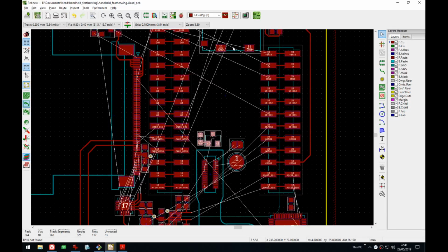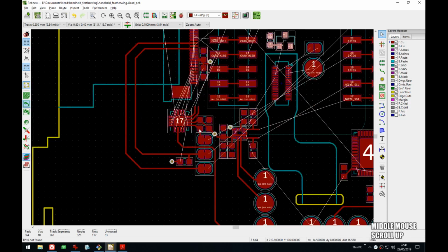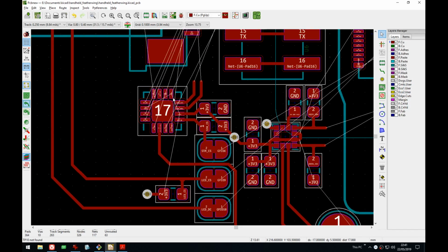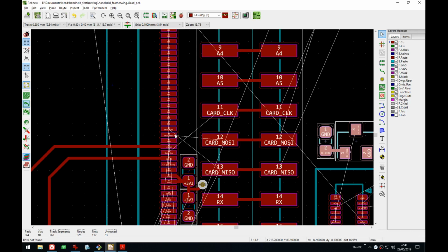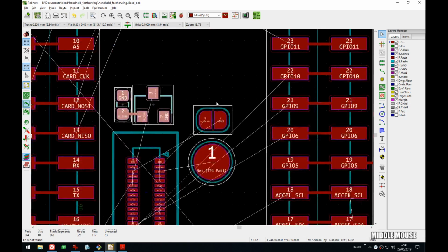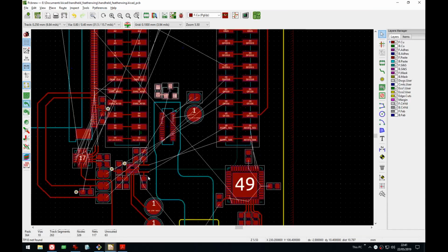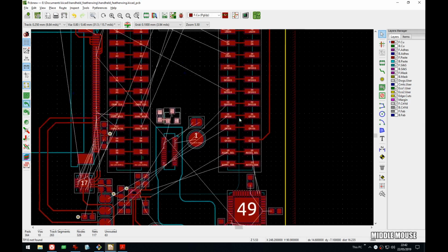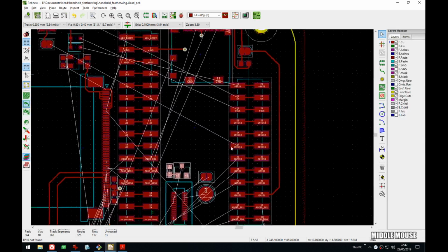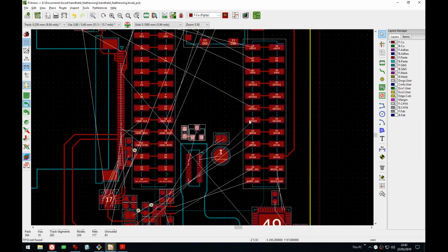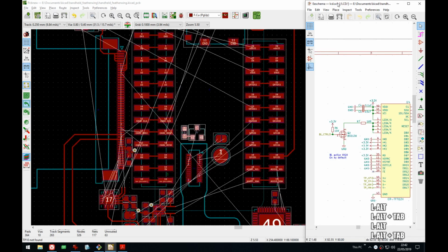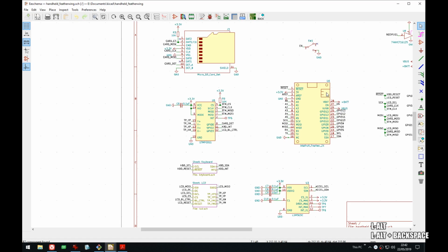There's gonna be some chaos here because the card, the LCD, and the GPIO expander have to go to the SPI. And then here we have the miscellaneous, well, the I2C, which could just go here and here. But then all the chip selects are here, and yeah, right, that's the NeoPixel. So I don't want to move these because they are on the same GPIOs as they are on miscellaneous feathers.